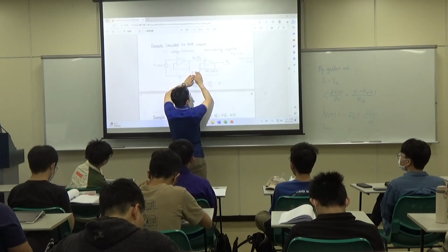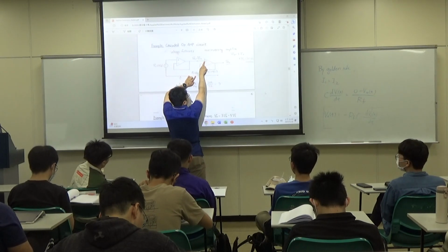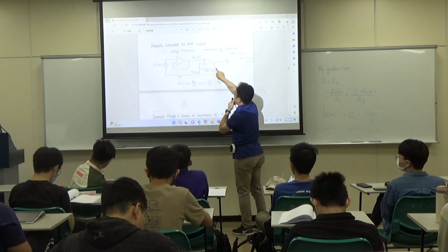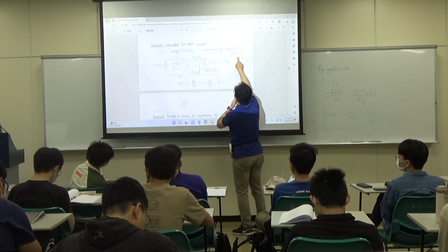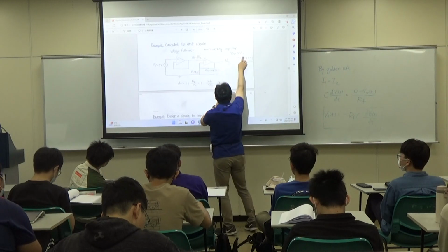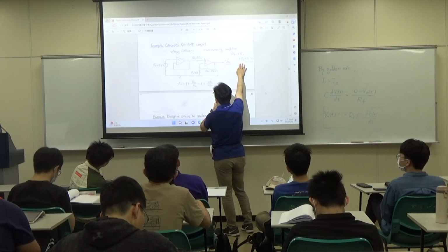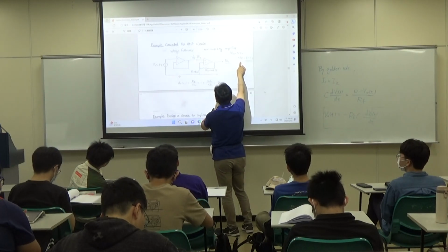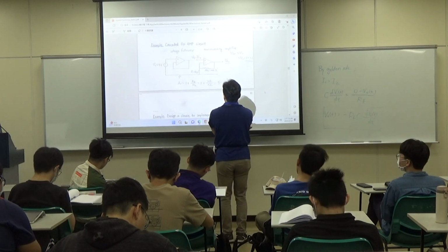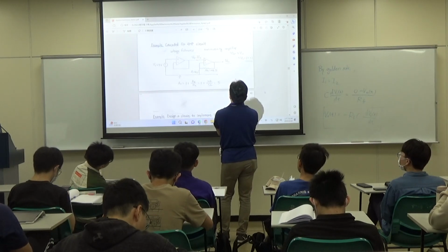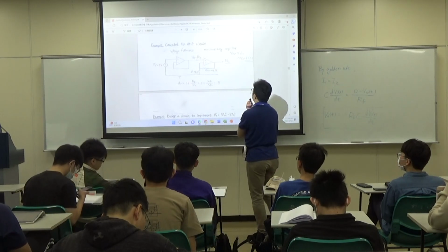Because right now this is ground, you provide voltage at the positive terminal. This is the non-inverting terminal, and so you can calculate the closed loop gain for this. So the overall VO2 equals 5 times VI2, which is 5 times VI1, that is 2.5 times 5. Okay, this is a little bit weird. Yes, it's right. It's 12.5 volts.